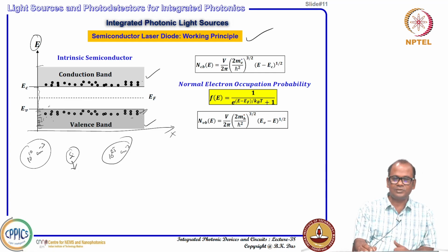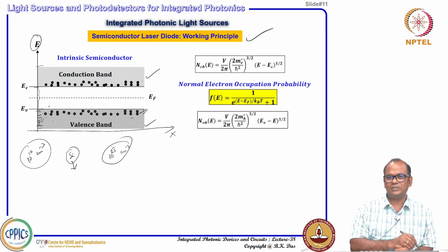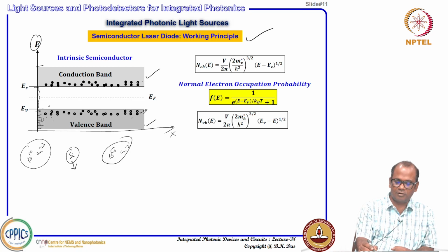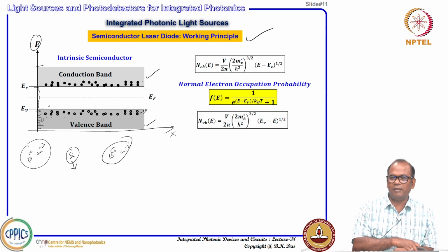So, that is the way a semiconductor is actually distinguished from the metal. How? Because in this case, in the conduction band you will get some number of electrons, and in the valence band also some number of empty spots. If you apply some kind of electric field, these empty points can also move. So, that can carry some current, and the conduction band electrons can also carry current.